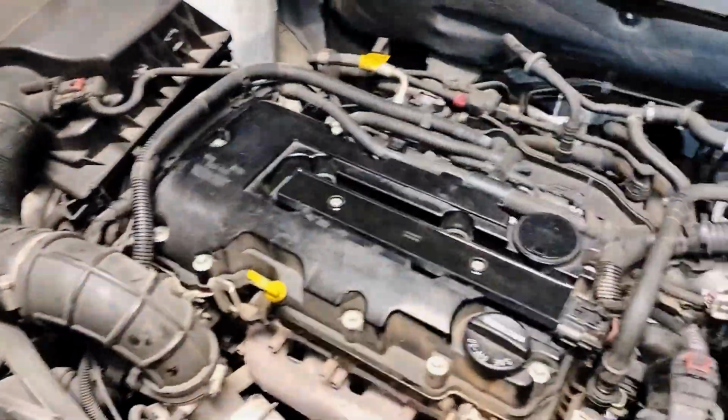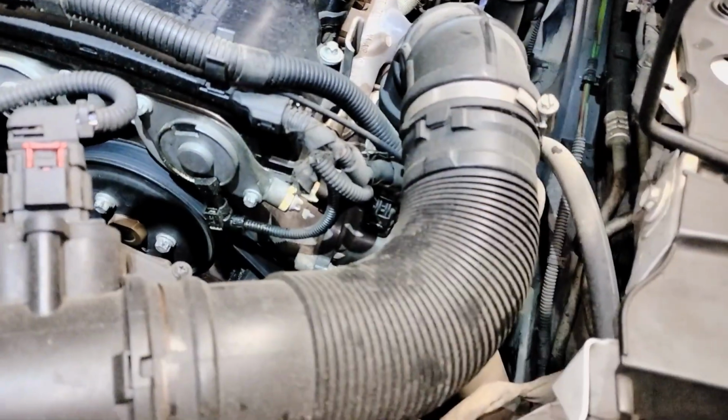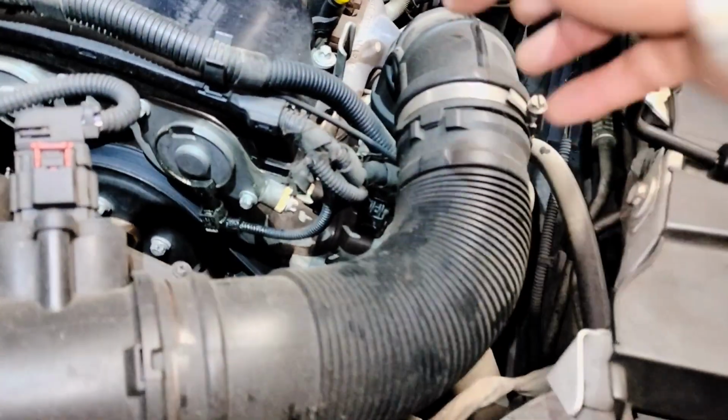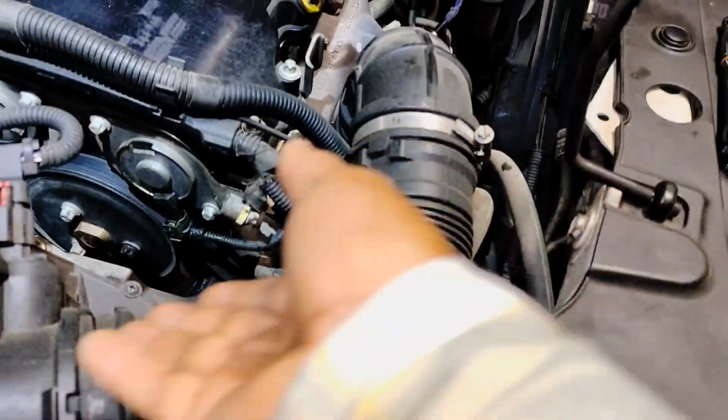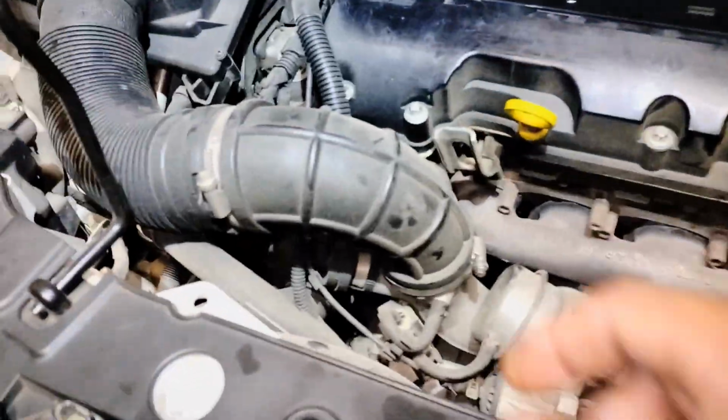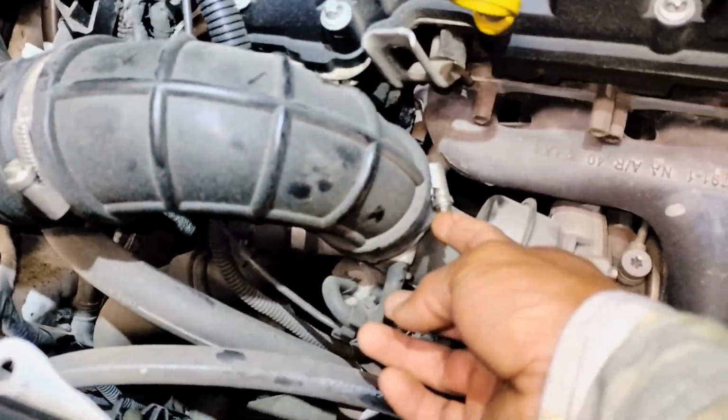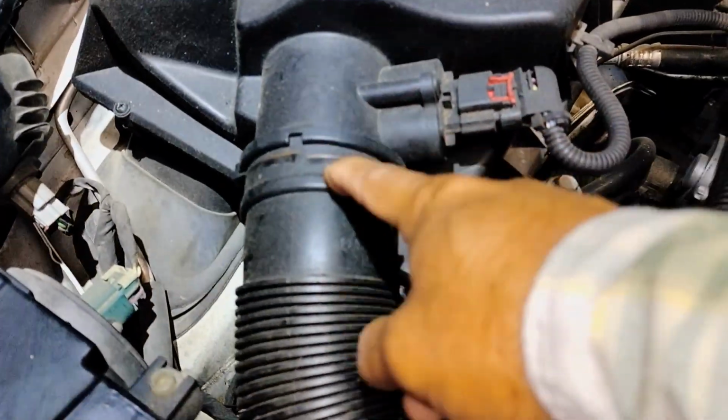Right here we are at the engine bay. This is a 1.4 liter engine, and the thermostat is located here on this side. That right there, that's a thermostat. So in order for us to access the wiring comfortably, I'm gonna remove this throttle body hose. There's just one bolt here, one clamp, and if it's a clamp here, then you just have to remove it.